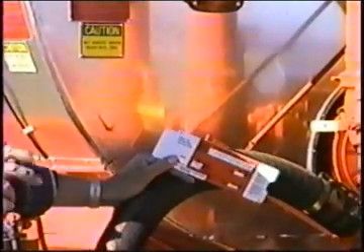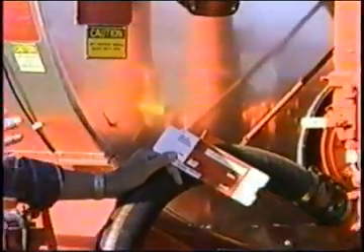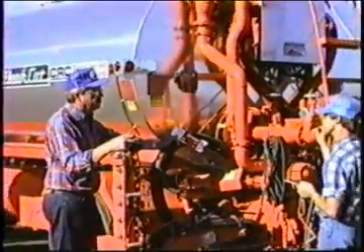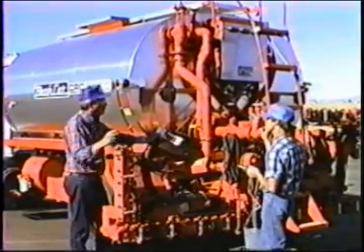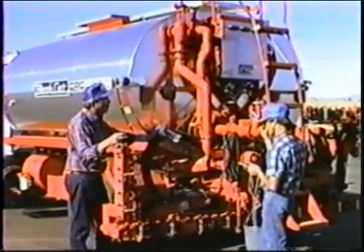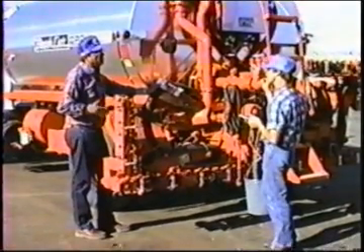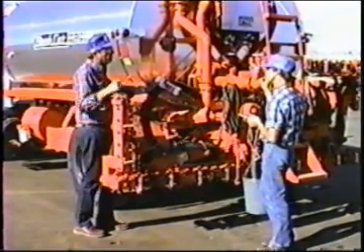It takes two things to create pressure. It takes a supply of the liquid, and it takes some resistance to the flow. That is, if we took the nozzle out altogether and pumped 135 gallons a minute through this spray bar with no nozzles in it, we'd see zero pressure. It'd all just be falling out on the ground because there's no resistance to the flow.